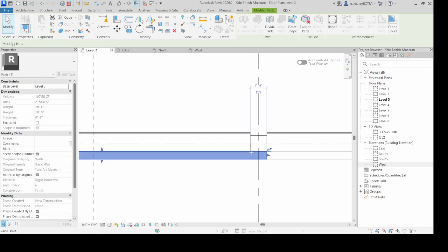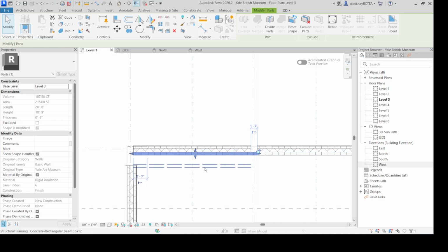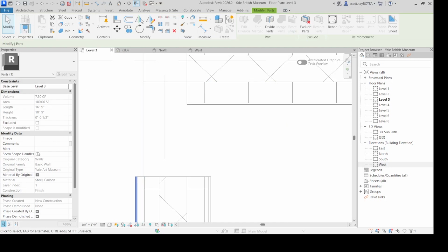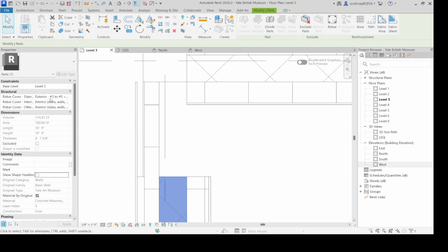Now this interior column's covered. I don't have to muck about with fixing that one. Now I come over here again. Unfortunately, it's each individual part, which is part of why I just try and do it on the corner walls. So this is going to take a second. Because we lined up the edge of our CMU with our column, it shouldn't create any conflict here. And now these last bits, I'm just going to have end right at the wall rather than keep going.